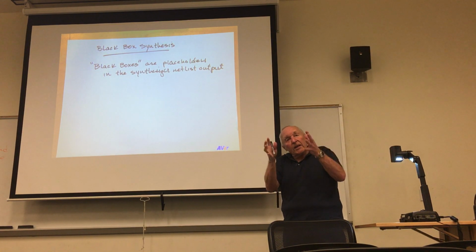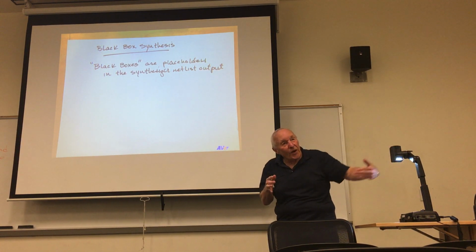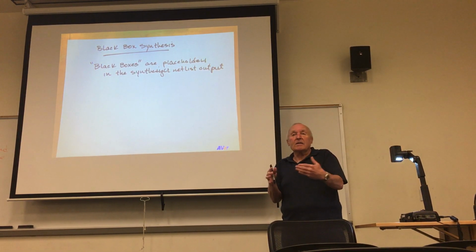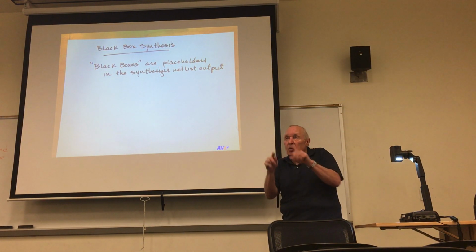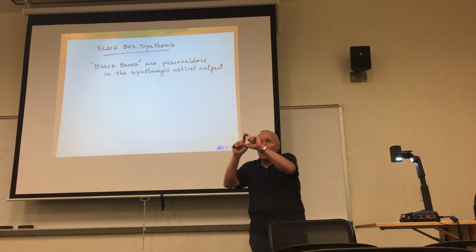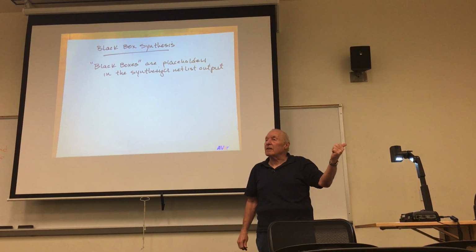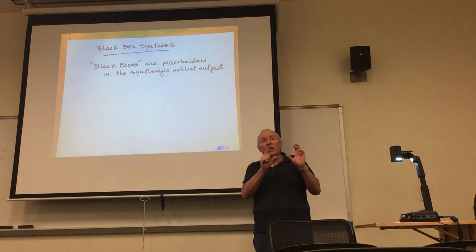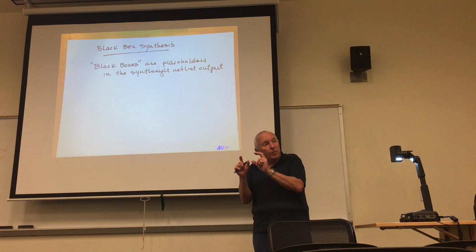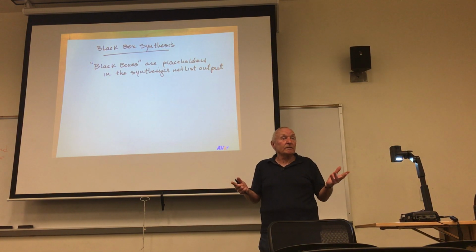Then when the netlist generated goes to the place and route tool, that's where the .ngc file gets input. Because place and route says, okay, you got a placeholder in here, and there's supposed to be netlist information on that core. Where is it? Well, you got that .ngc file. That's where it gets input. So the .ngc file actually gets input to the place and route tool, not to the synthesizer.